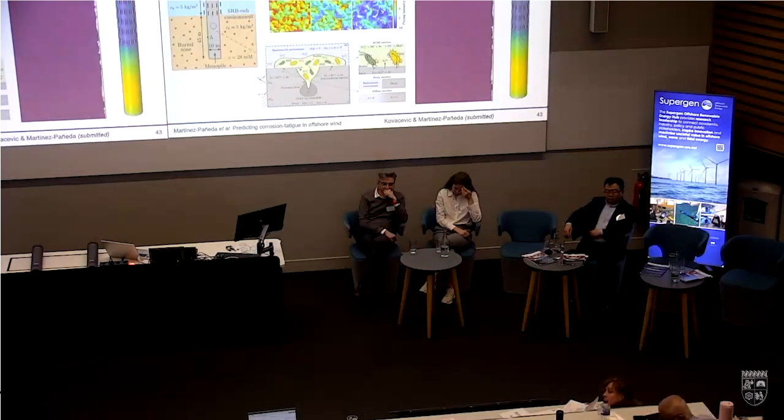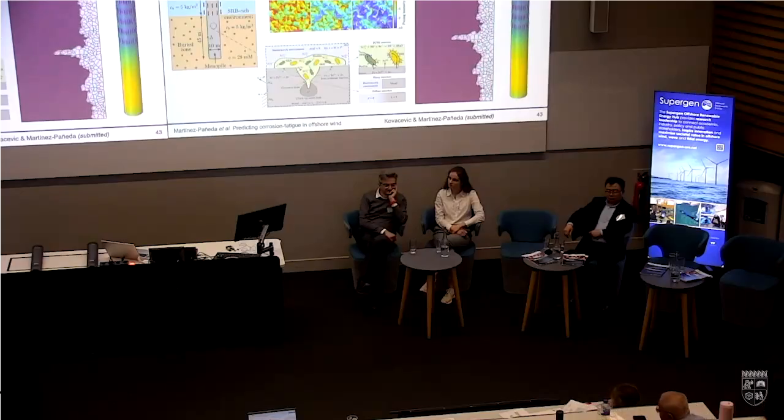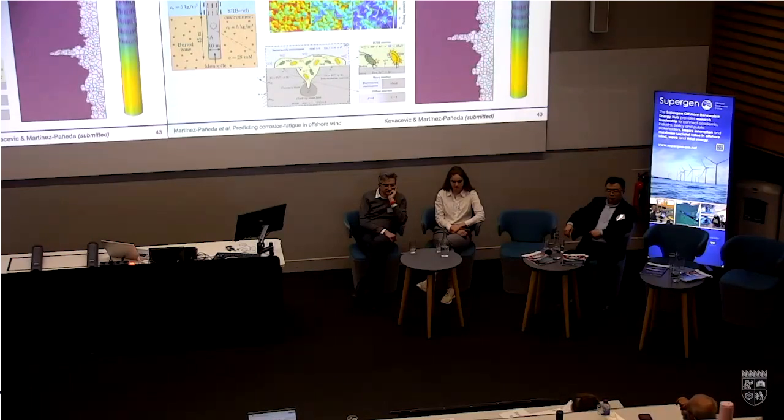And the last sub-project is one that I find very interesting because we developed the first model for microbiology-induced corrosion, where we enriched the electrochemical description of our problem to include the reactions happening in these bacteria-rich environments. It's very relevant for offshore wind, of course, because microbiology-induced corrosion is what triggers localized pitting and corrosion in offshore wind, and we were able to show that the model is able to capture that. You can see here we're able to capture the evolution of the corrosion front, very similar to what I showed you before. You see here pitting and pit to crack transition. We can do this in 2D, in 3D, while resolving the microstructure, and we're resolving over periods of decades the effect of your sacrificial anode or your cathodic protection degrading in time.